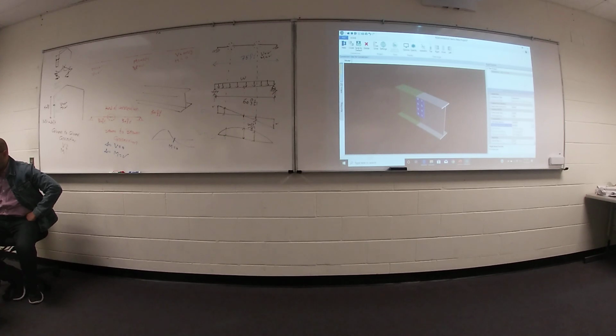That's fine. Then open this arrow to choose the properties of your plate section. I'm talking right now about this plate. What is the material? What is the thickness? Maybe your thickness is 0.5 inch. What is the width? It's 6 point something. So we can choose 10 to see what will happen. What happened? It becomes wider. And also, what is the depth? The total depth. What is the number of plates? Is it single or double?